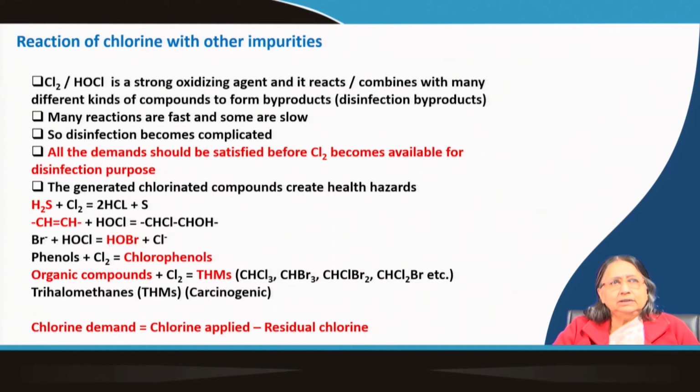So, that is also not known long time back, but now we know that this type of compounds, you know that what is THM, why this name has come. You see that all the compounds, it is chloroform CHCl3, it is bromoform CHBr3, it is the dibromochloroform or the monobromo chloroform. Okay. So, here you see everywhere 3 halogen atoms are there, 3 chlorine atoms, 3 bromine atoms, 2 bromine, 1 chlorine, 2 chlorine, 1 bromine.